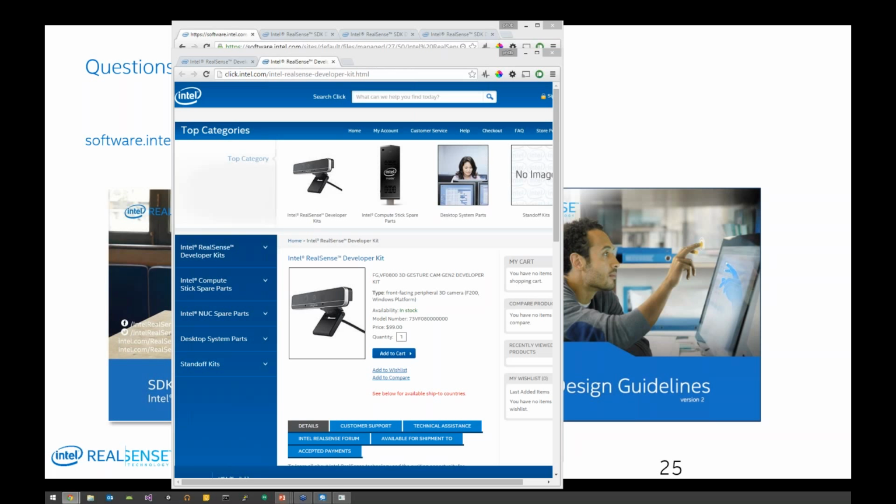Then you can use both modules. But for the full gesture recognition, it's especially complicated to make it work because people may want to do swipes really quickly. But when you do the full hand tracking, it's limited to less than 1 meter per second, and it needs all the field of view to be operated. That's quite sad actually, but I would recommend not to use the swipe gestures from the SDK right now.